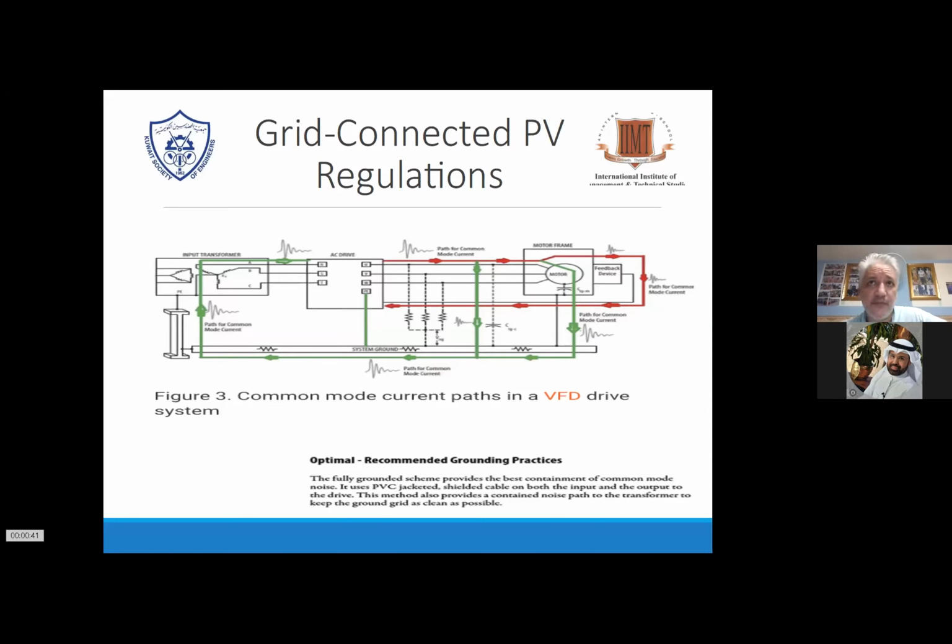I had a case where the system had been running for 4 years, with Suntec modules and Sunny Mini Central inverters from 10 years ago, and a 30 kilowatt system was added. So it was 300 kilowatts running with almost 1100 kilowatt hours per kilowatt peak, which is quite good in Germany.